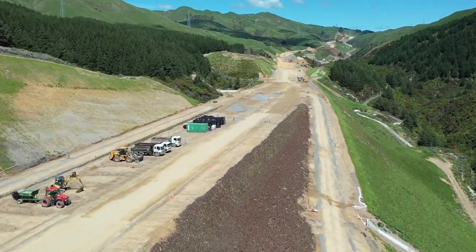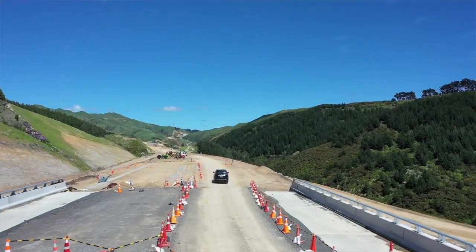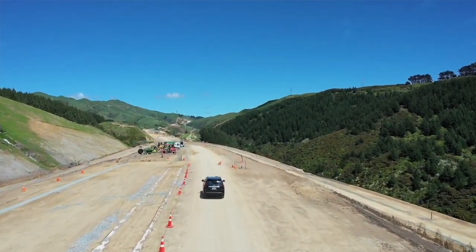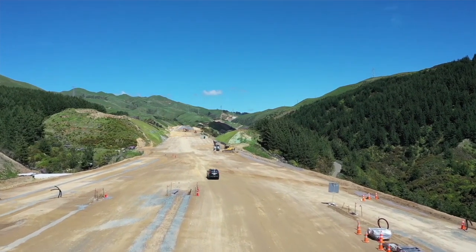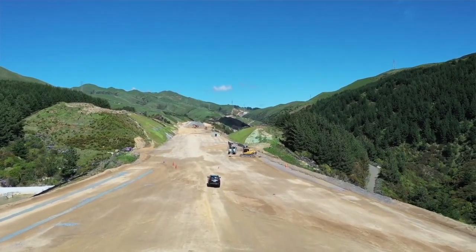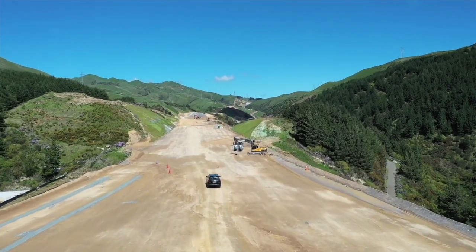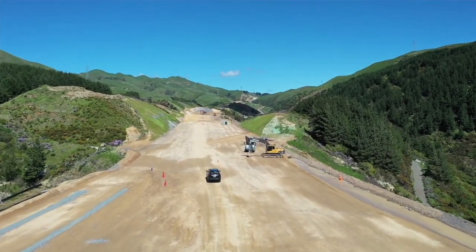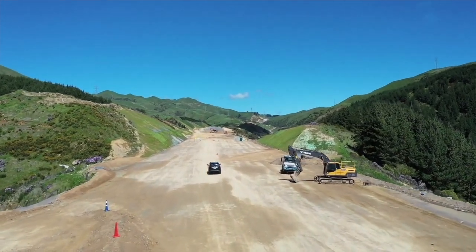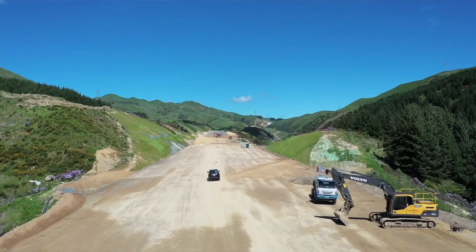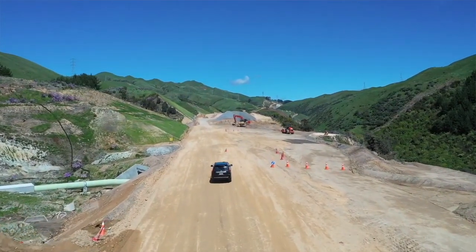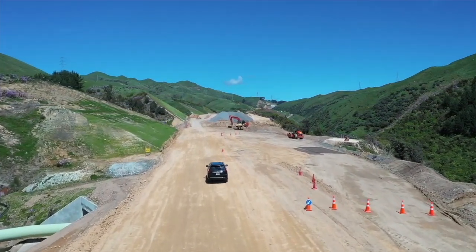or the designated land. The Transport Agency will need a range of approvals under different acts. There's the notice of requirement as described previously to get the land designated, and at the same time the Transport Agency will seek resource consents for the earthworks and for the structures such as bridges which are required to build and operate the project, and also for permanent stormwater discharge from the road once it's built. Other resource consents might be around management of contaminated land, diverting streams and groundwater diversions and discharges. And all the information described in the AEE will be used to get these approvals.